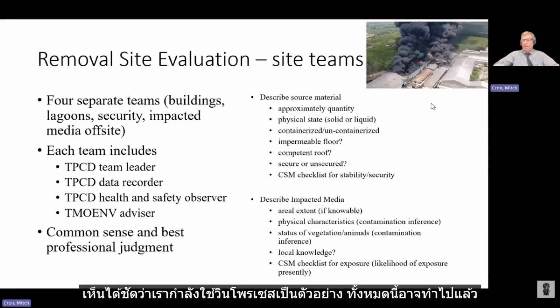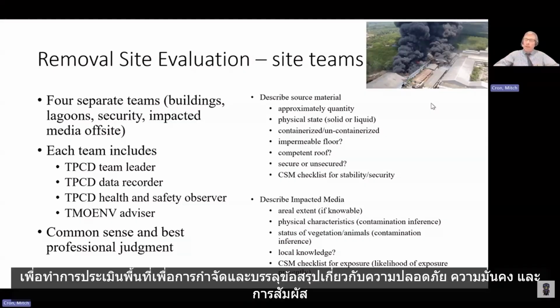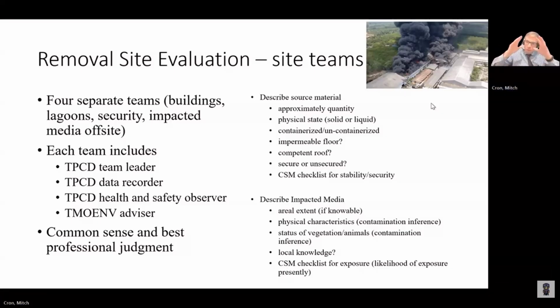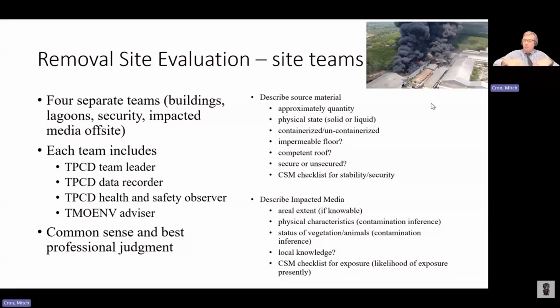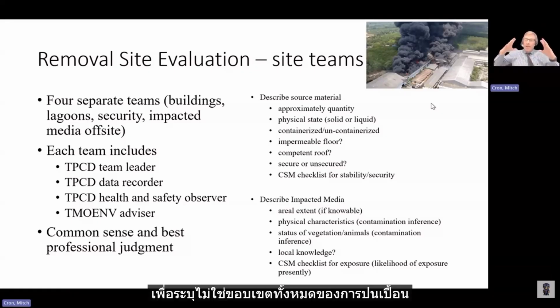All this may have already been done, but what we're trying to do here is practice a process to perform removal site evaluation and to reach conclusions on security, stability, and exposure. And finally, for folks analyzing impacted media, I also wanted them to use the CSM checklist as one tool, plus other tools that you may have used in the past when you're analyzing contaminated sites. The CSM checklist, when I put it together, the idea was to find a simple tool to identify not